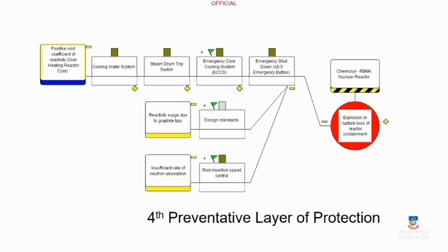So here I'm illustrating how you can use a bow tie to dissect a threat and an incident to get to understanding the controls, how things could go wrong, and then focus on why these things could go wrong and what the process safety elements are that could lead to these controls being compromised. That is the key purpose of, number one, this presentation to you, and number two, the assignment that I've set for you.